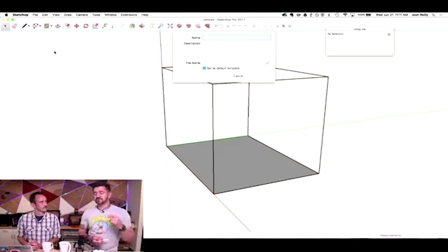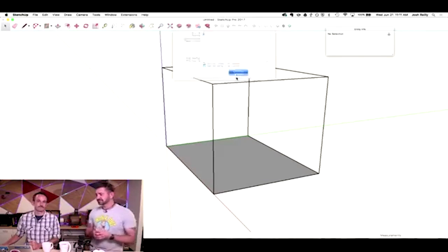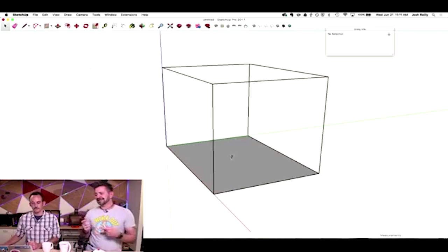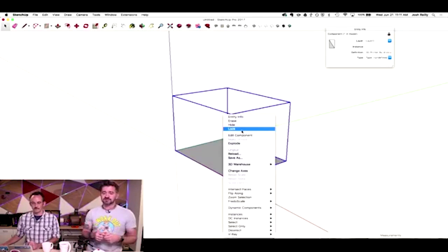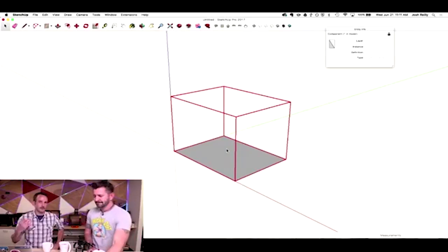One of the things you want to make sure you don't do is take that geometry that Josh has on the screen and export it to your printer. This could be done a couple different ways. One thing is Josh could take that and actually lock it, which is a nice thing because then I'm not going to accidentally select it. I'm not going to merge geometry with it. It's going to stay isolated. So you can't interact with it in SketchUp unless you right-click and choose Unlock.